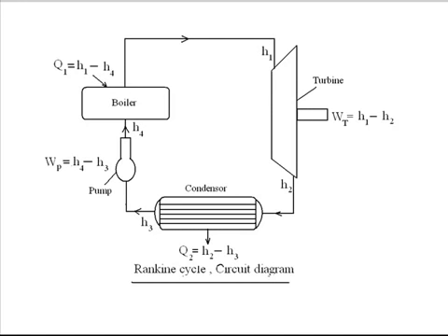It is simple. See, steam is entering with enthalpy H1 and exiting with enthalpy H2. Steam enters with enthalpy H1 which is greater than H2 because some amount of enthalpy will convert into work done by the turbine, and the steam will come out from the turbine with the remaining enthalpy. So the specific work done by the turbine will be H1 minus H2.